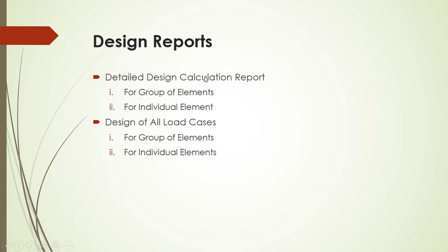For detailed design calculation report, we can have a report for a group of elements like a group of drop panels, a group of column strips, or we can have it for an individual element also. We can also generate design calculations for all the load cases, again for a group of elements or for individual elements.